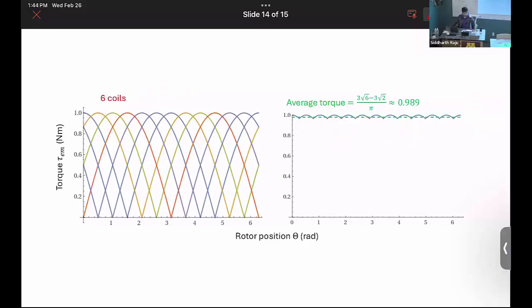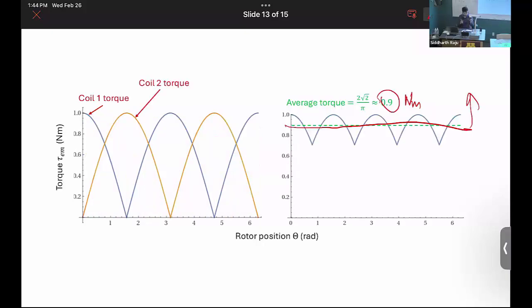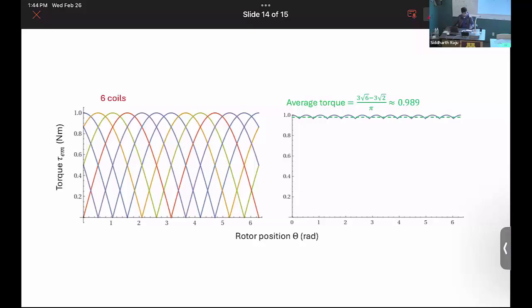So we just put more conductors which are displaced, right? In this case, we have 12 slots in this rotor. Previously, we had 4 slots. Here we have 6 sets of conductor loops. So we have a whole bunch of conductors which are phase shifted by 30 degrees, 30 degrees, 30 degrees, and so on and so forth. So you create a whole bunch of loops like this.